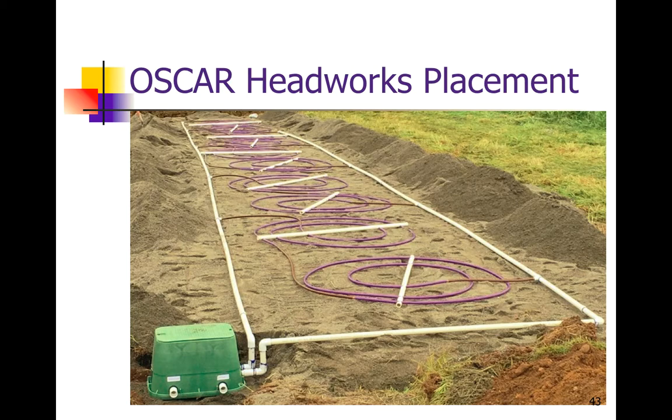The problem is the sand does not give us very much insulation in the wintertime. We have had some problems with headworks freezing, and they've only been the ones that we buried in sand. And a lot of times, a good portion of the box is sticking out from the top of the sand, or from the surface of the sand.